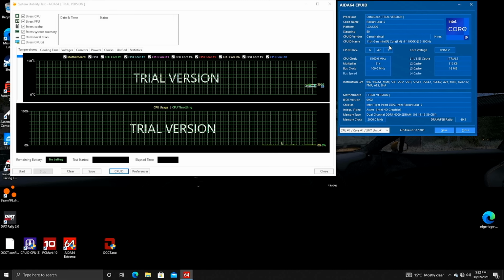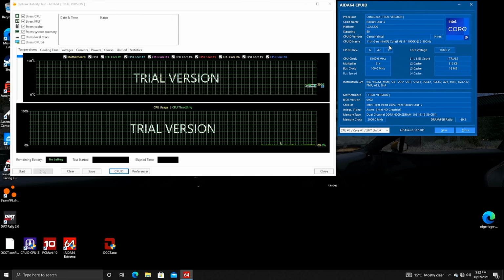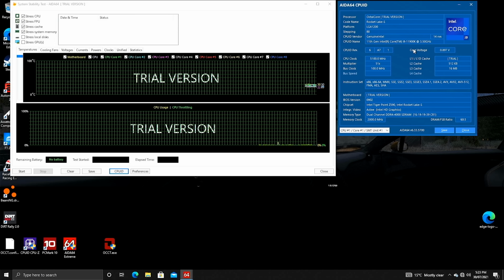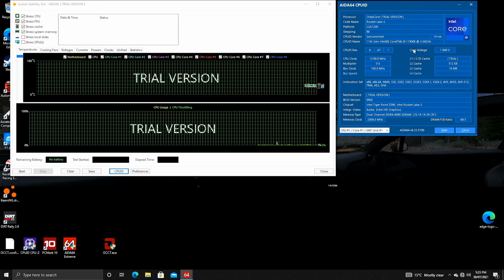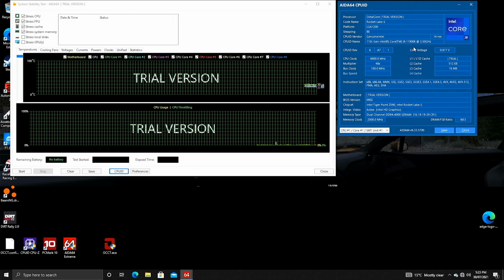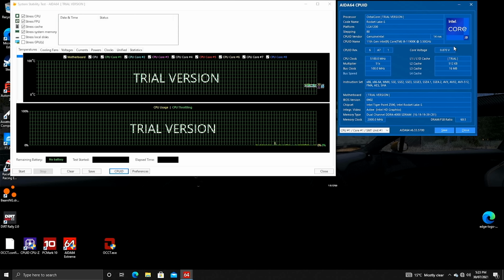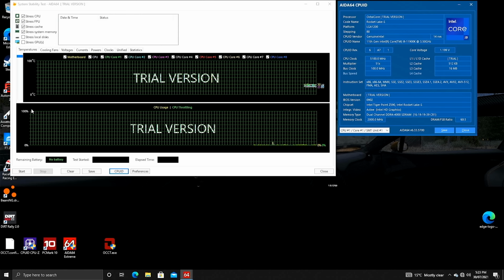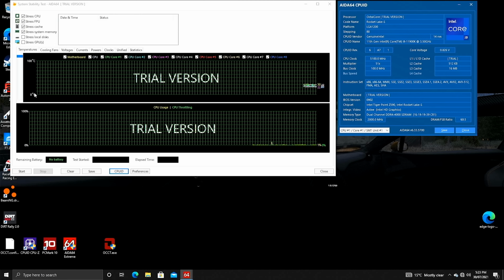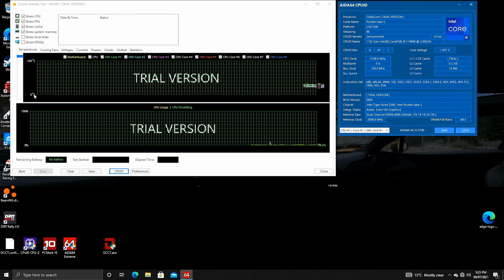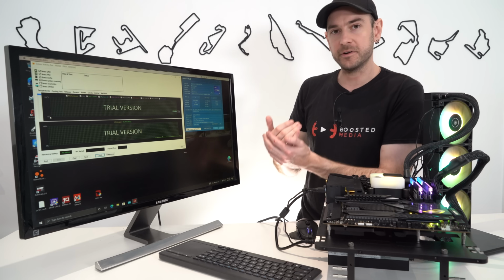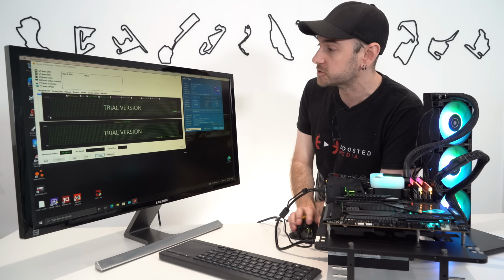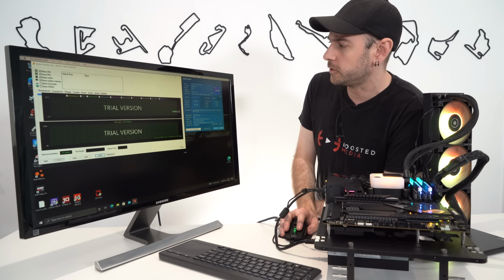We are using CPU clock speed scaling at the moment because we haven't adjusted any of those settings just yet. And we can see also the core voltage is adapting relative to the load on the system and the core frequency as well. So that's the reason why we're seeing our core voltage jump around. When we begin the stress test, we should see that clock speed jump up to the maximum allowable under the settings that we have for all 8 cores being active. Remembering again that depending on the number of cores active will ultimately determine the maximum clock speed. We should also see that core voltage jump up too.